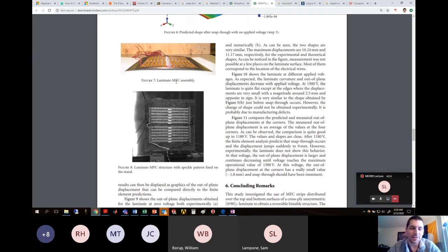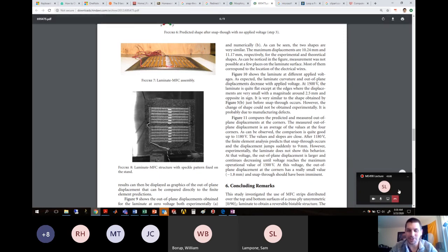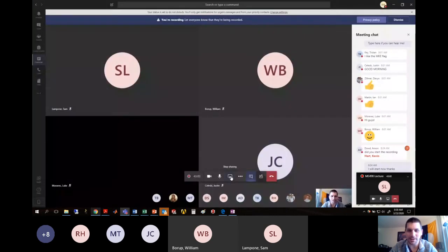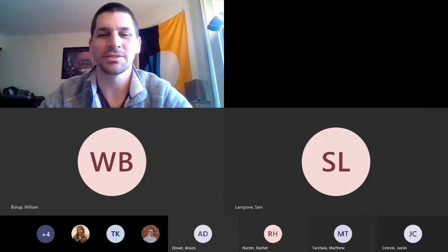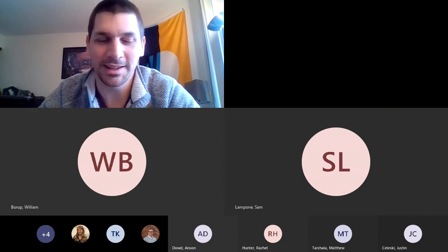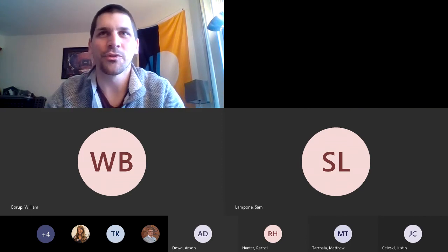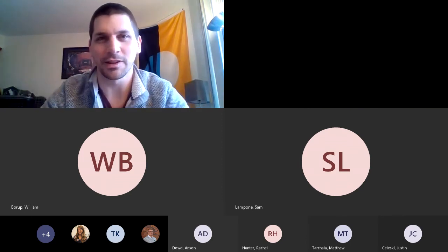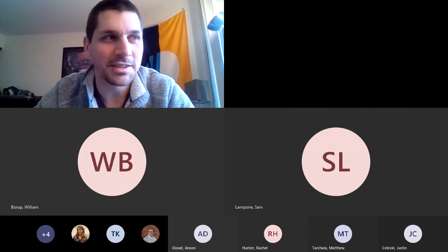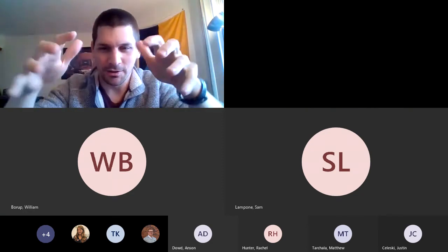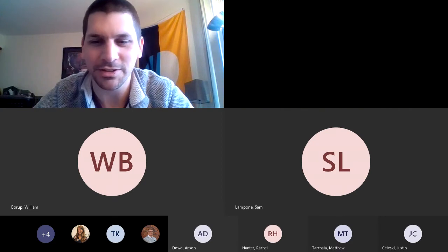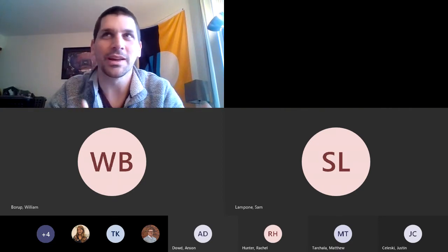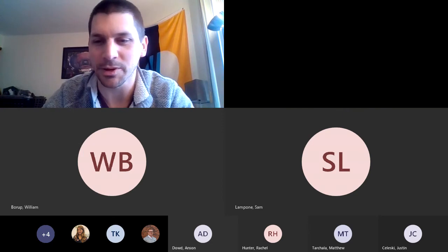So this composite that we manufactured looked seemingly innocuous, doing this 0, 0, 0, 0, 0, 90, 90, 90, 90, 90 sort of thing. It looked rather innocuous, but in actuality, there's a lot of learning that can be done with this composite because there are different coefficients of thermal expansion in the different directions of the lamina. And it creates this composite that ends up being curved and actually has two stable configurations of curvature just because of the way that it cools down after the manufacturing process.